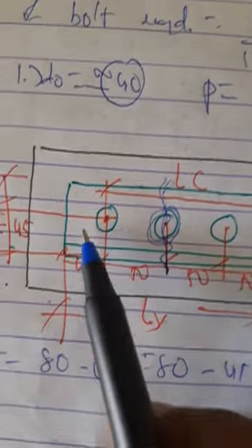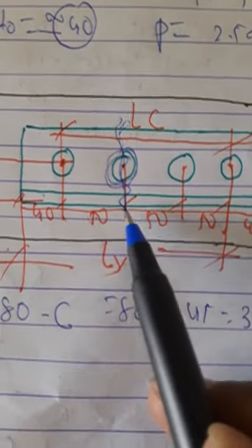Now the third strength, block shear strength. So Lv is equal to, here look at this value, this is Lv. Lv is the distance of this bolt to this end. So 50 plus 50 plus 50 plus 40, that is 40 plus 50 into 3, so you have the answer 190 mm. Lt, length in tension, is nothing but the connected leg out minus c. c is 45, so you have the answer 35 mm.